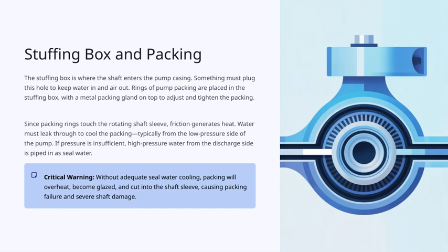Overheating causes the packing to become glazed, which can cut into the shaft sleeve. This not only leads to packing failure, but can also cause severe damage to the shaft itself. So, maintaining proper seal water flow and cooling is essential for the longevity and safe operation of the pump.